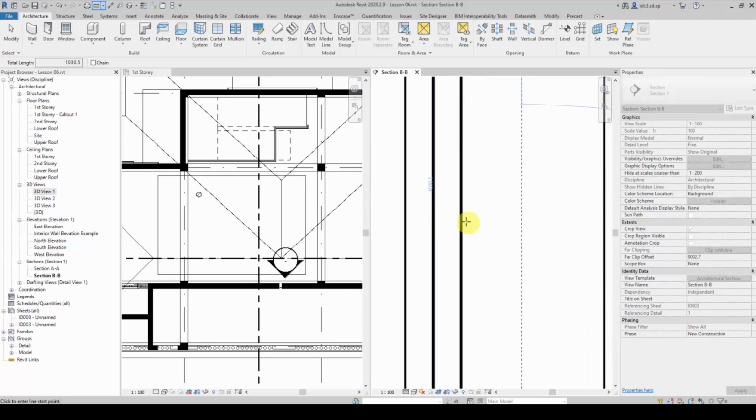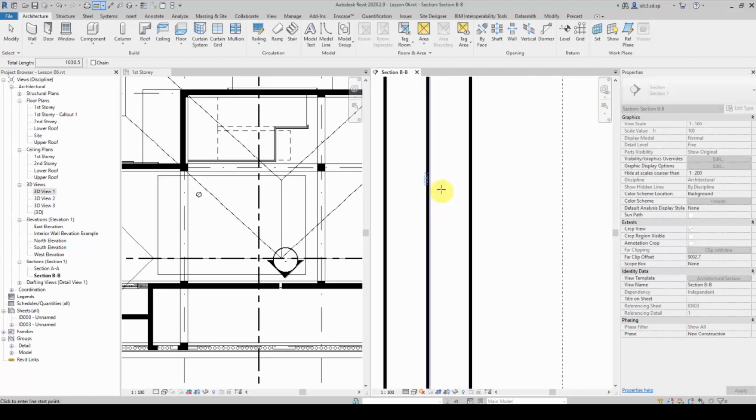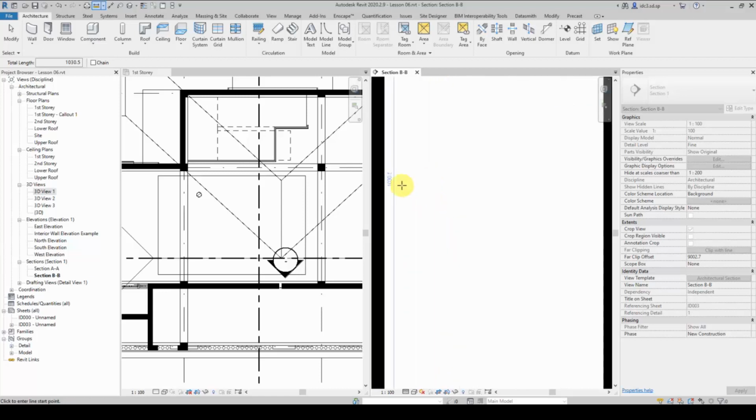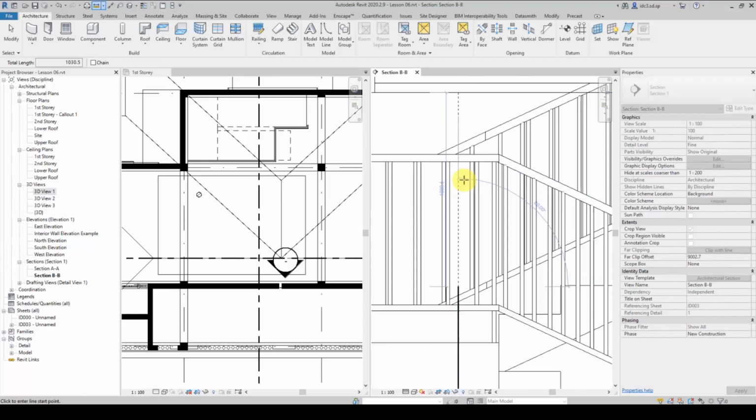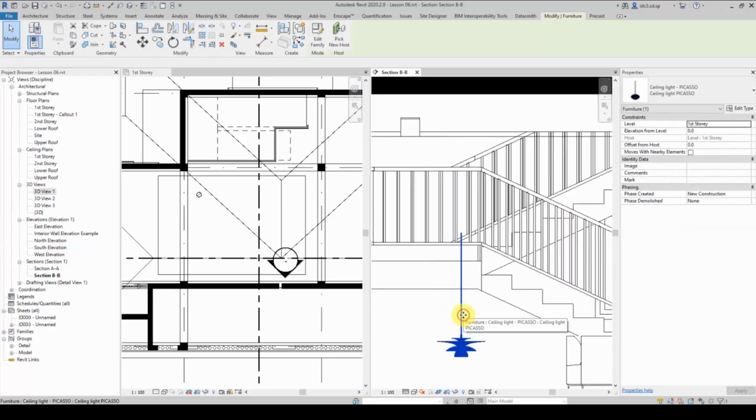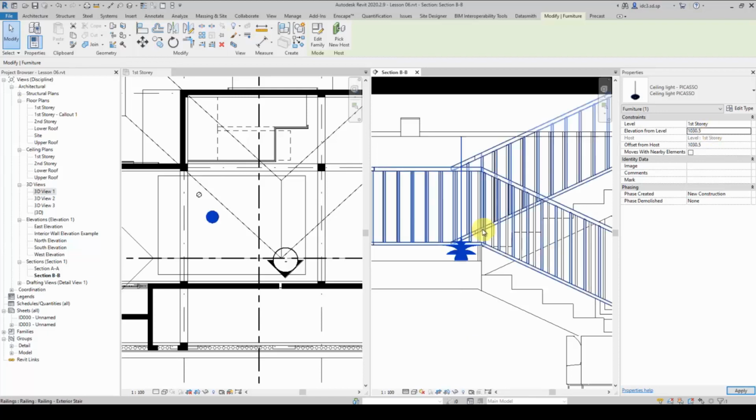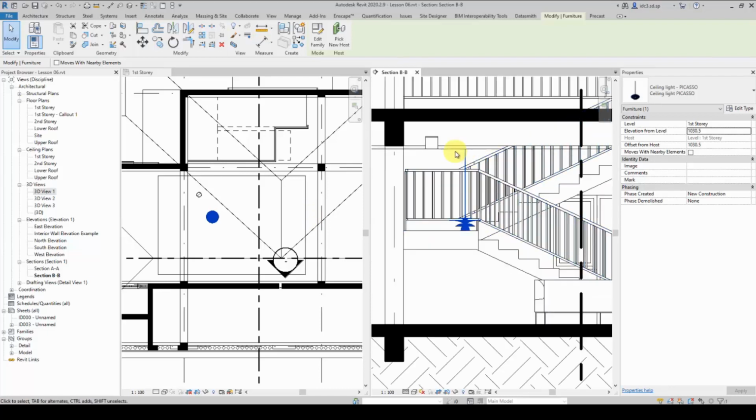Generally, I would recommend, if you already have a ceiling set up and you know your ceiling height is proper already, then we will want to use this option called place on face. It will literally just stick on the face itself. That would do the job generally. So I'm going to click on place on face, like that.